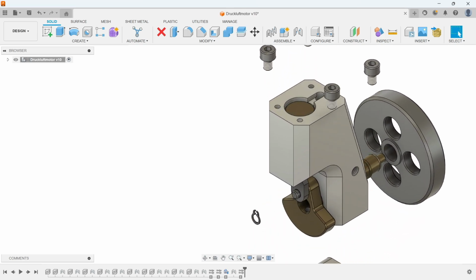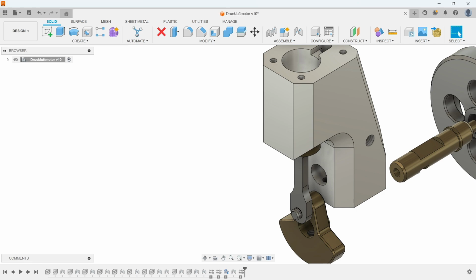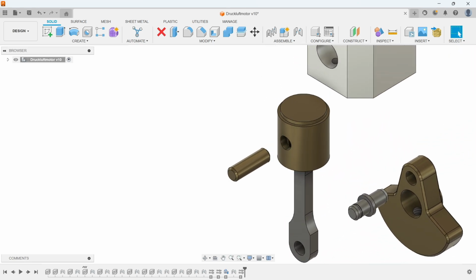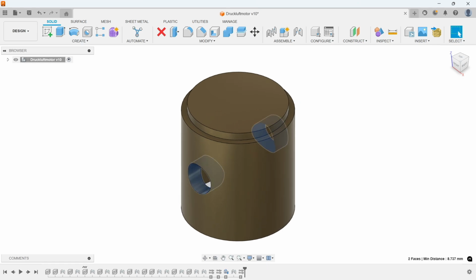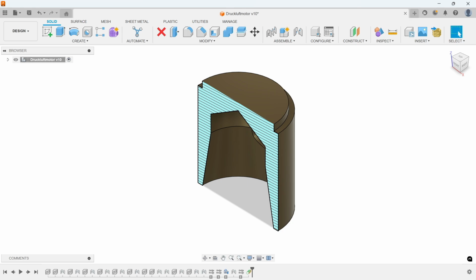Today we take a closer look at the piston, the heart of our compressed air engine. We will show you how you can insert the through hole into the rotationally symmetric piston in 3 different ways. In doing so, you will learn 2 new functions: creating a plane tangent to the outer surface and cutting the piston in the sketch view.